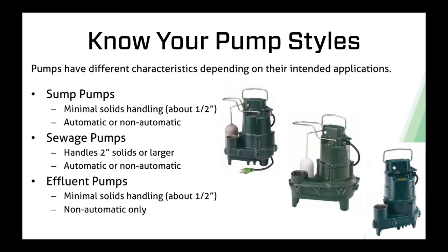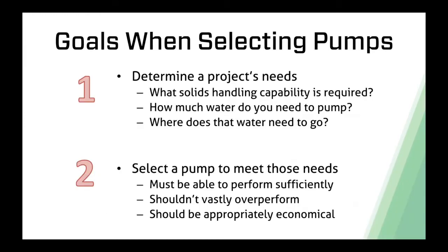What we want in an effluent application is for that pump to be fully submerged at all times. So we're going to use a different kind of float switch, one that will shut off high enough where the water still is above the top of that pump. And it will keep the corrosive gases from attacking the seals and even the cast iron itself.